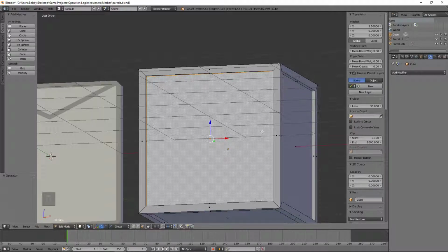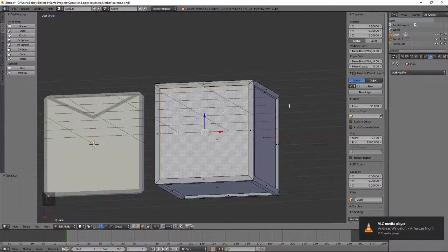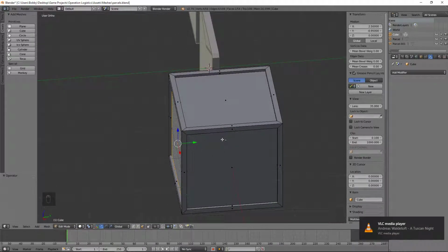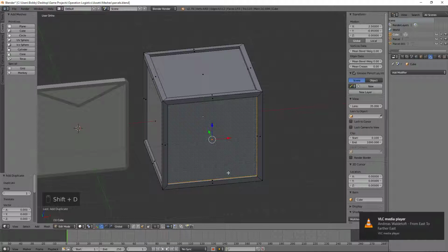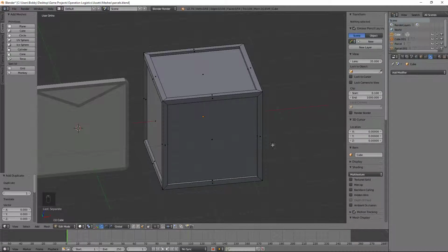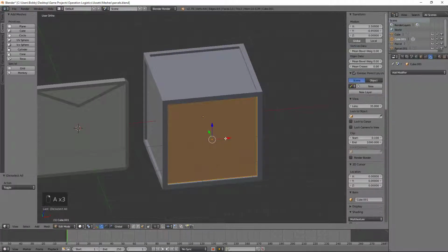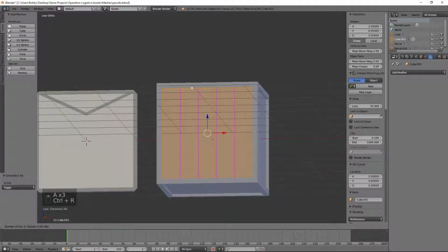We'd want to detach the face and then put in a loop cut. And then essentially just set that origin to be here, and then rotate it around a bunch of times. It'd be pretty doable. Let's go ahead and do it. I'm going to detach that out with P, the selection, and I did duplicate it before I brought it out, just so you're aware. And let's say that this is made out of...